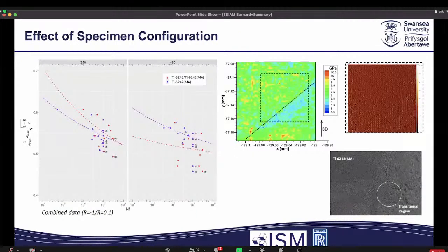In terms of using the additive material as a surrogate or on its own, it was interesting that at ambient and moderate temperatures, the composite specimens slightly outperform the solely additive specimens, whereas at the extreme temperature, the presence of the wrought material in the composites shows a reduction in the HCF performance. The relative behavior between the composite specimens compared to the conventional Ti 6246 is consistent across all the temperatures that we tested at.